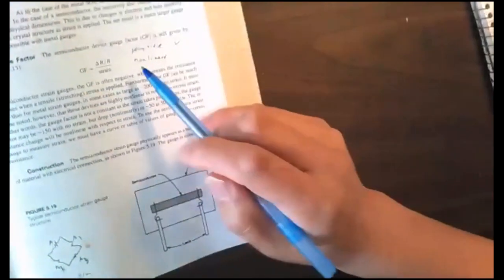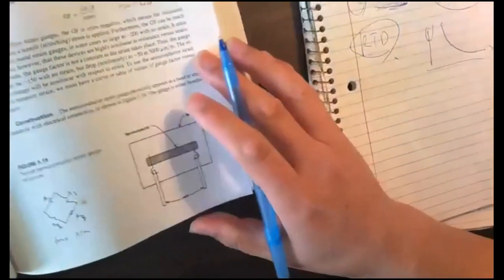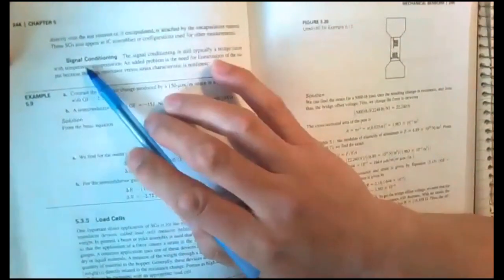But we have a problem with this type of sensor. It's nonlinear. The resistance changes significantly, but it's not linear. And that problem can be solved by digital circuits. Today's digital circuits are so complicated, we can put thousands of components right here and make very complicated calculations of filtering or DSP. So not a problem, this nonlinear problem can be solved by digital signal conditioning.